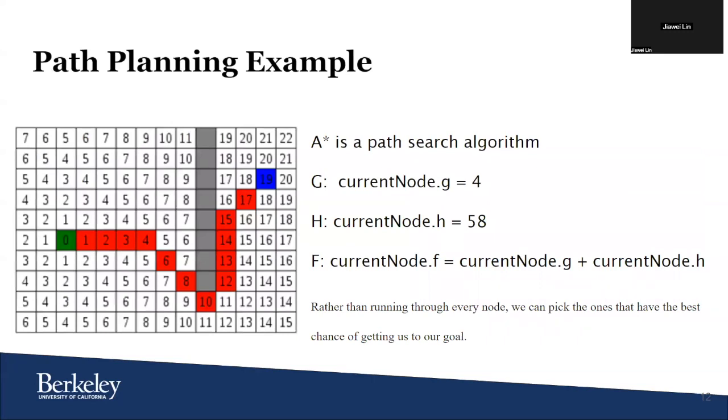We put the formula into the A-star algorithm. In this algorithm, which is used for generating the shortest path as reference, the topology of the car is captured by a top view camera, and the positions of the JetBot and obstacles are found. The camera result is converted into a grid with a given resolution. The grid, starting position, and the destination are the input of the algorithm, and the output of the algorithm is the shortest path, which is calculated by minimizing the total cost of the node shown in the figure.